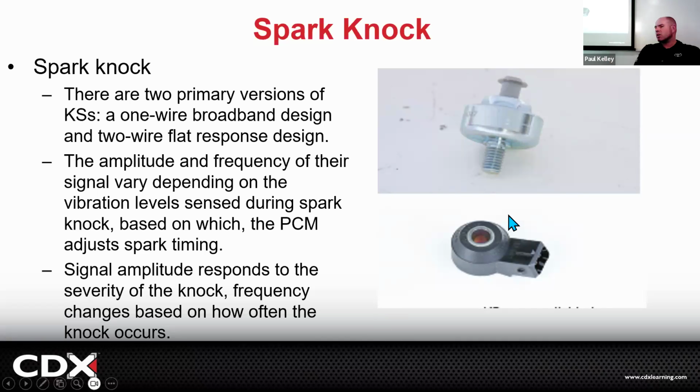So this knock sensor is part of the ignition because it's a major input to the ignition system. We lost the pickup. Sure. That's exactly why. Older cars didn't have that technology. Newer cars do, so they're a little more dummy proof, but what it also does is allow the manufacturer to try to run as much advanced timing as possible for better fuel economy, better emissions. But if it does overdo it, it can back it off because it's got a microphone listening all the time.